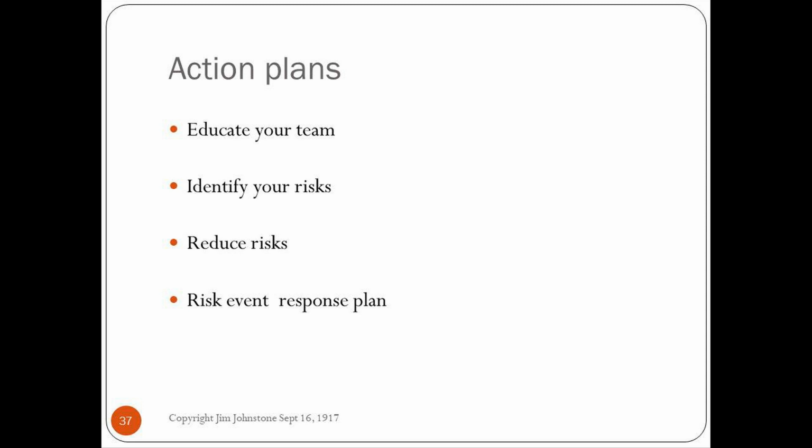The second thing you've got to do is maybe use some group technology. Group things together, either by suppliers in a certain location or all suppliers that make a certain kind of part. Maybe it's a critical part that is made for you. Identify the risk using the techniques that I've shown you, and then prioritize those risks by assigning the risk priority number, and then systematically reduce the risk on your high-risk areas.